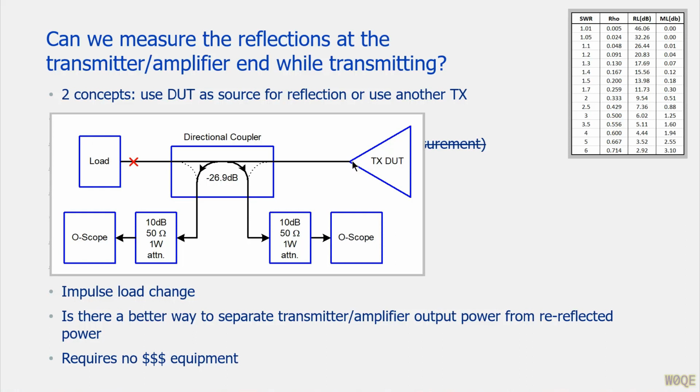I transmit here. I'm in a continuous state, 100 watts going out of this transmitter. I see a signal coming back here. It's very, very weak, indicating a very good load. I see my full power forward wave coming out here. I can see the phase of it very nicely on a scope. I throw this switch, and in the case of when I did this, it was a high power reed relay. It dropped in under a millisecond.